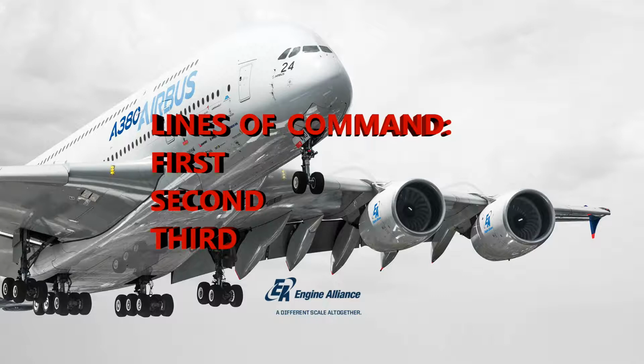The motor is connected to 3 actuators, by the way. You have 3 actuators per thrust reverser. That's going to be for each side, so that's per engine. And in order to unlock those tracks, there's also a fuse box that's installed below the E-track, and that's just going to give protection for that system in case there's an electrical problem.